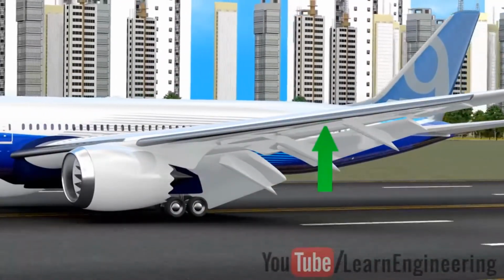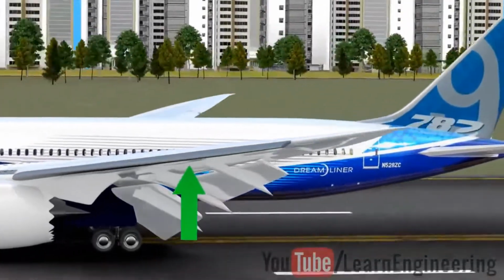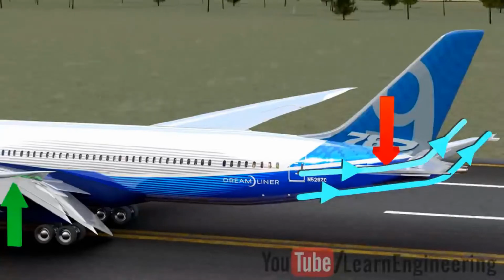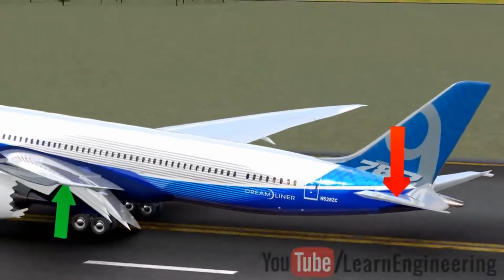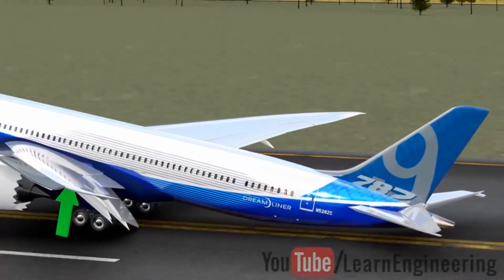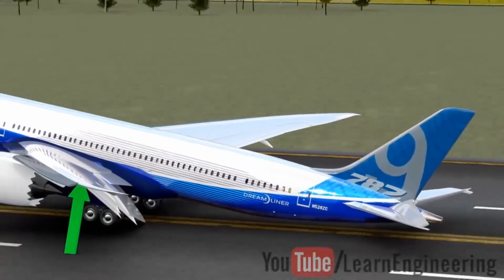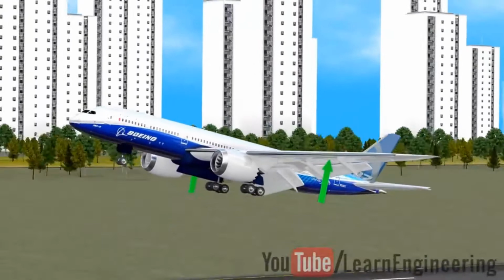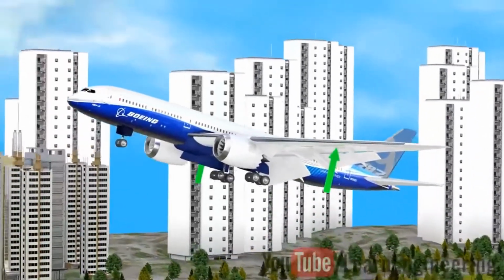When the airplane is ready for takeoff, they activate the elevators upwards. The tail force tilts the airplane as shown, and the angle of attack of the airfoil will be increased. The lift is suddenly increased due to this, and the airplane takes off. Usually, an angle of attack of 15 degrees is maintained for the takeoff.